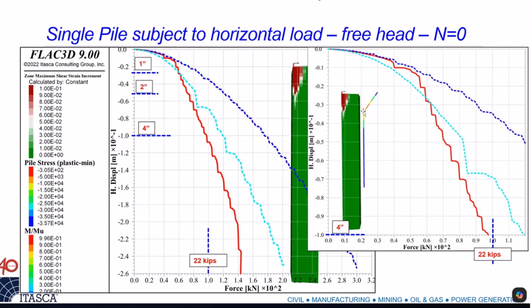So while we focus on this coupling springs saga, we don't even consider something that is way more important, which is the nonlinear behavior of the structure, especially after cracking. The concrete reduces the stiffness significantly. As you can see here, you get essentially half of the force available, and you get a much softer response because the pile starts cracking all the way up to breaking. All right, I just wanted to emphasize this.